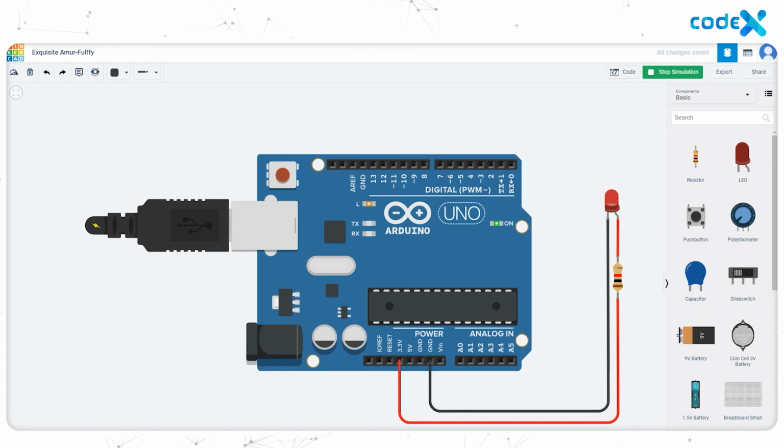Here we designed a simple circuit to turn an LED on using Arduino. Can you believe it? Oh my god, you became a creator now. Nothing becomes a good creation until you have your logics correct. If the LED was connected directly to the 3.3 volt pin, it would have burned out. So the connection of an LED using power pins is just similar to the connection of an LED using a battery. You can try the 5 volt pin to turn the LED on.